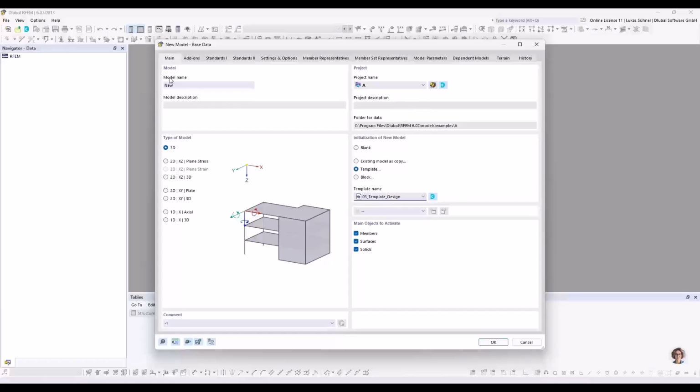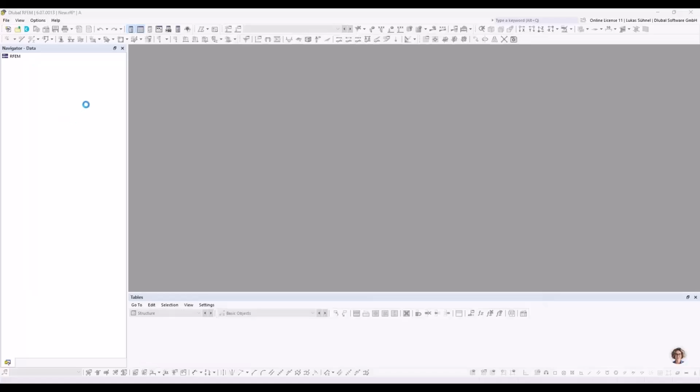So basically you create an empty file into which the information from that template file will be imported. And let me show that as well. And as a result, your file is not empty anymore. You get these load combinations, the protocols, maybe even materials and cross sections, whatever comes to your mind that you want to have as a default in a new file can be saved in a template, and that will be imported afterwards. Takes a moment.